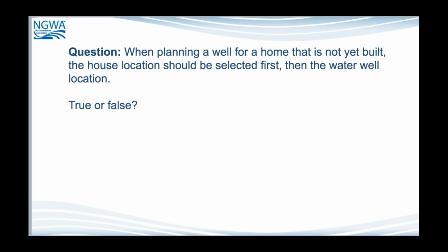In my state, it's not allowed anymore to put a well underneath the ground, to put a well into a pit, or to terminate the well at ground level. You have to have that well 8 inches above grade, 8 inches above whatever the final grade is. That is where that well has to terminate to be code approved and a properly constructed well in my state.